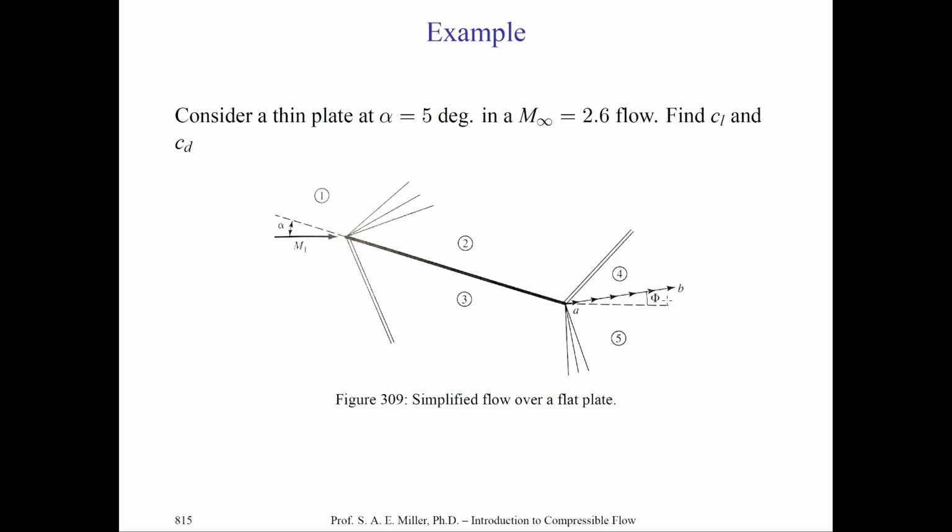So the velocity of the flow does not return to the parallel direction. This is because we have the requirement that the static pressure in 4 and 5 be equal. If the flow returned to the horizontal incoming direction relative to the original flow in 1, the velocity vectors would be parallel before and after the vehicle, then of course we could not hold the condition of static pressures being equal, which is a requirement given the assumptions we made of compressibility and, of course, inviscid flow.